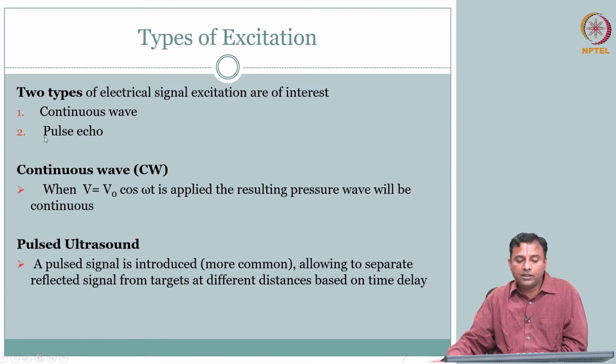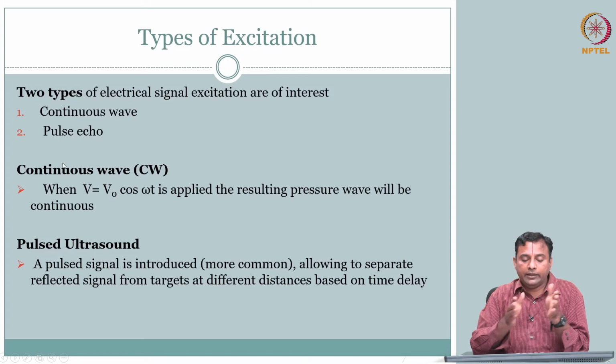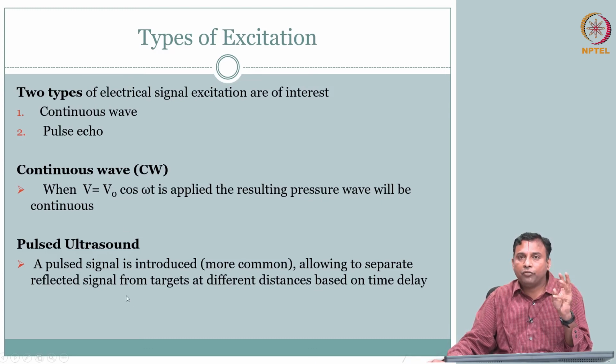Okay, what is pulsed ultrasound? I just apply a cosine, right? That we already saw. We apply a particular frequency of a few cycles. A pulse signal is introduced, allowing us to separate the reflected signal from targets.